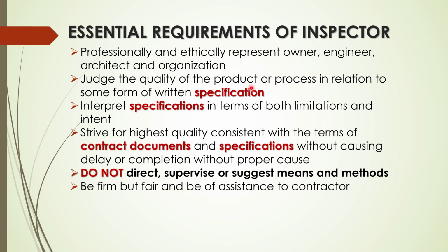Judge the quality of the product or process in relation to some form of written specification. Interpret specification in terms of both limitations and intent. So this can get gray. This is where the contractor will ask questions, and you ask questions of the engineer to make sure, what is the intent of that specification? You need to know that. So if you don't know, ask questions.